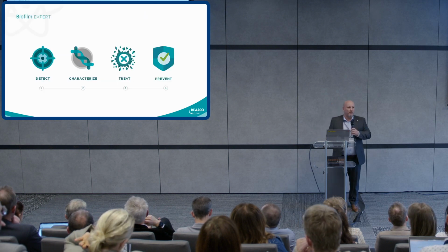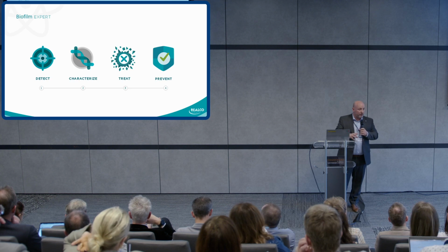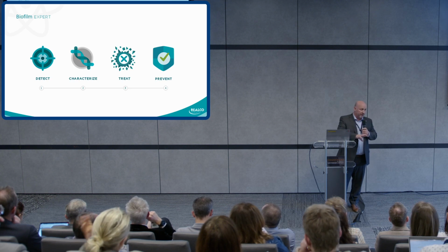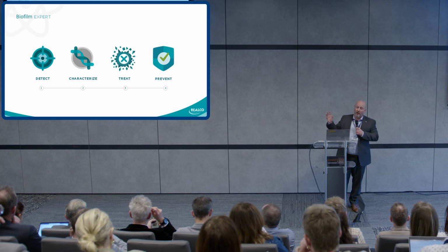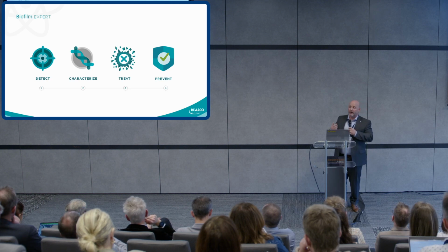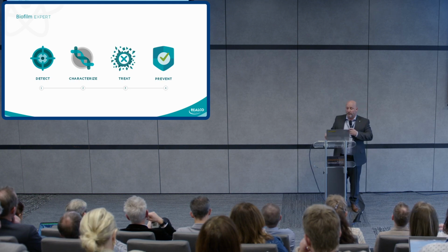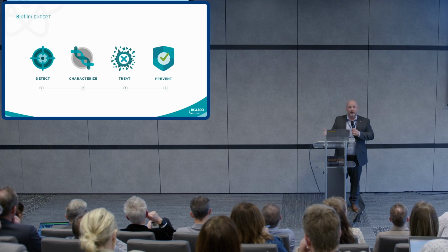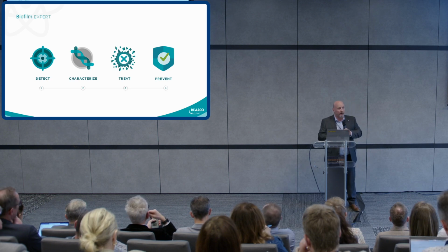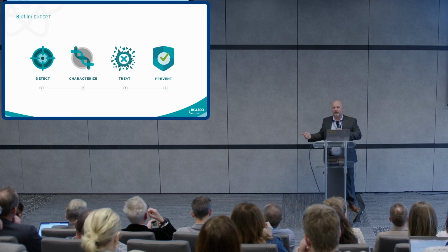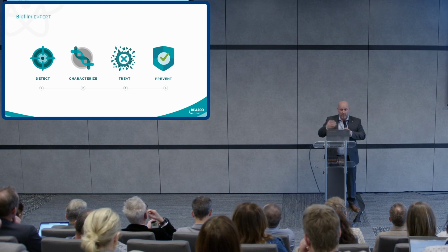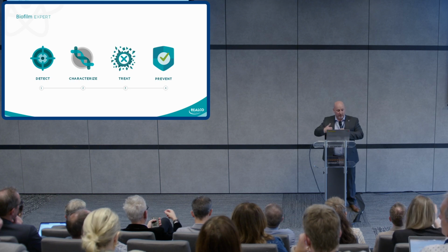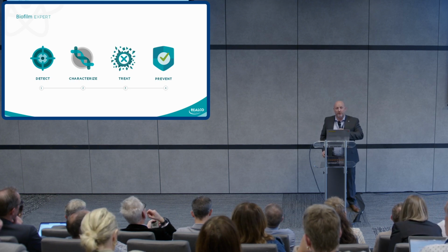So the process we recommend is, first, you do a detection. It will be different for open surface and closed circuit. After that, we characterize. We try to understand what kind of germs I have, to understand where they're coming from. You treat, so you eradicate the biofilm, and you prevent this biofilm from regrowing again. Because microorganisms are present, you cannot avoid that, and they will start to regrow and maybe pollute your production site.